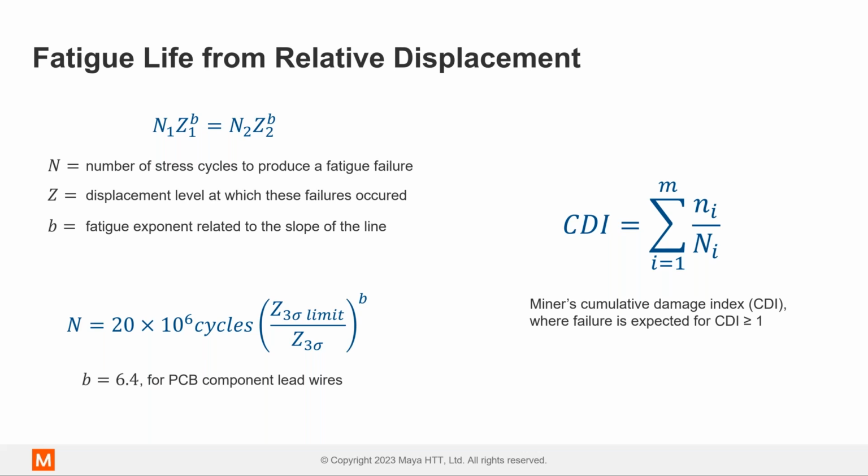You can also use, if you noticed, I requested positive 0 crossings, the number of times that my displacement crosses 0 in the results. You'll get positive 0 crossings as a frequency component too, the number of times per second. You can use all those to calculate your cycles.